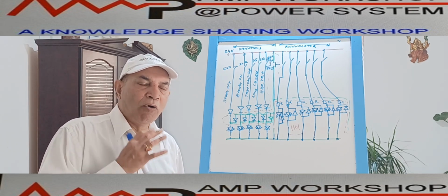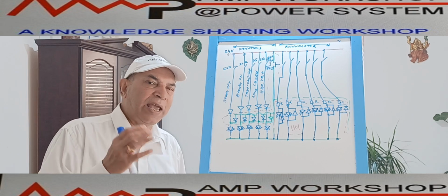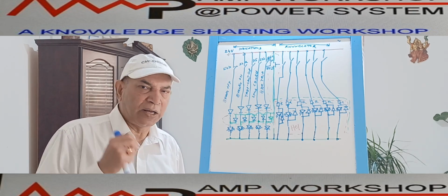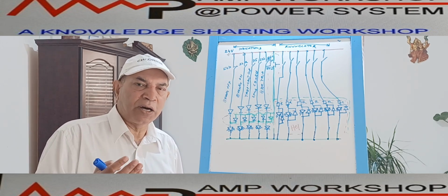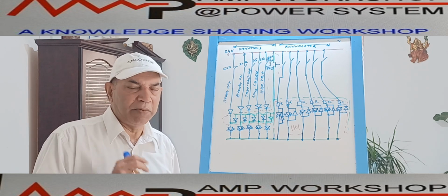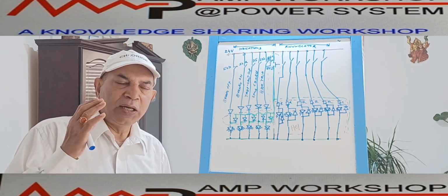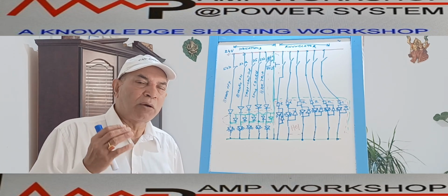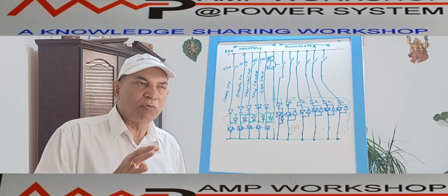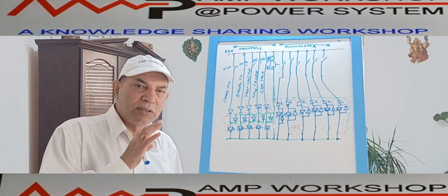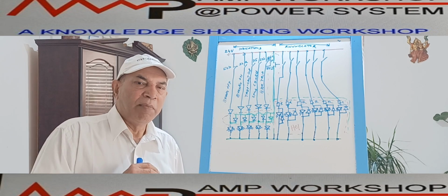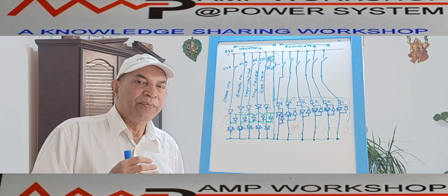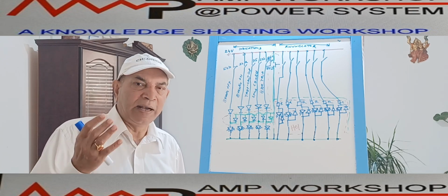It is a well-proven, solid state device. So nowadays, all the indication lamps we are using are LED type, and LED lamps are available in different colors: green, red, amber, and white. Normally, when we monitor the healthy condition, we use green lamps. When the green lamp is on, it means the signal is healthy.